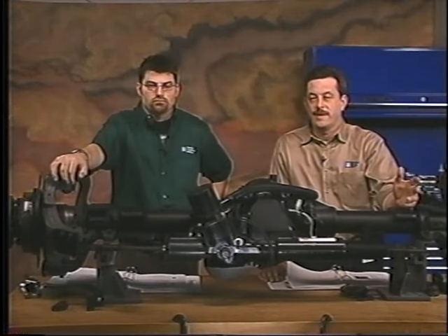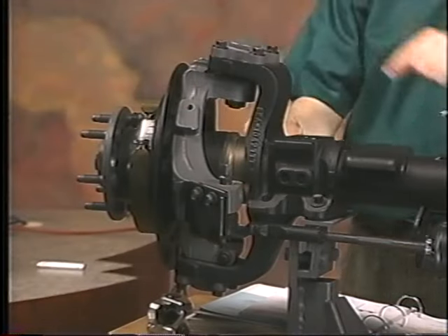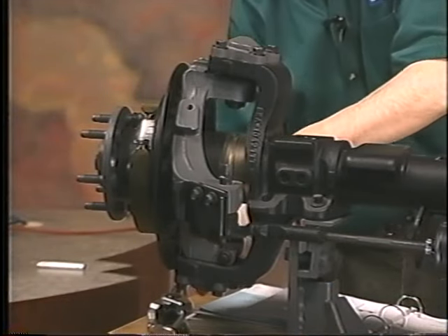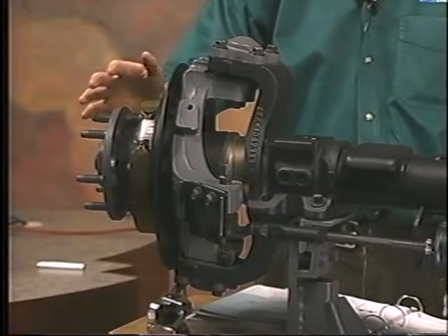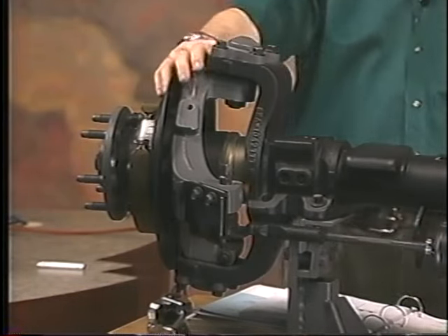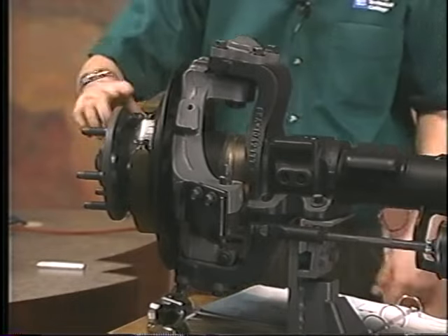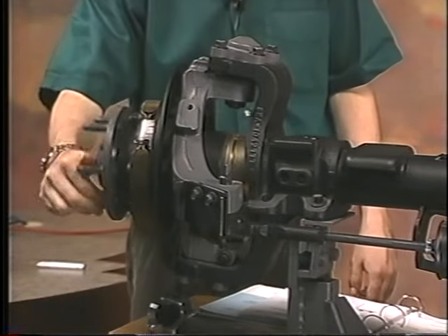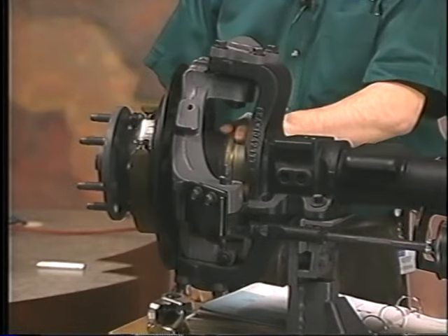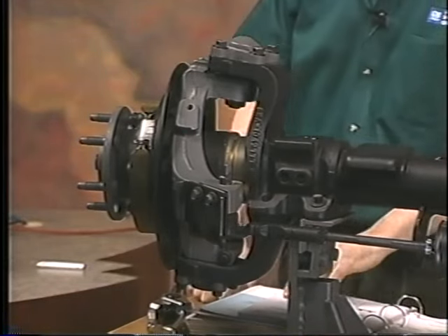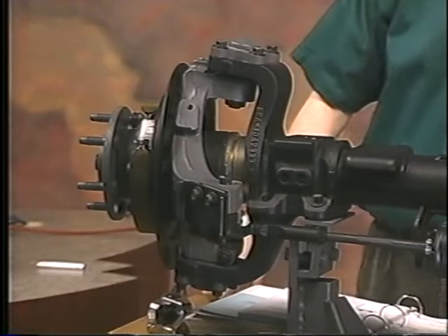Now, first off, what do we got? Well, we've got ball joints here. See those upper and lower ball joints. Definitely different. And we've got the spindle in between those two. Now, on the outer edge there, we've also got a wheel bearing. Again, not typical. It's very much like our front drive wheel bearing. Same idea there. We've also got to have a quarter shaft. They call it a quarter shaft because it only has one universal joint in it. And it's pretty well protected. It's in there, you can see. Okay?